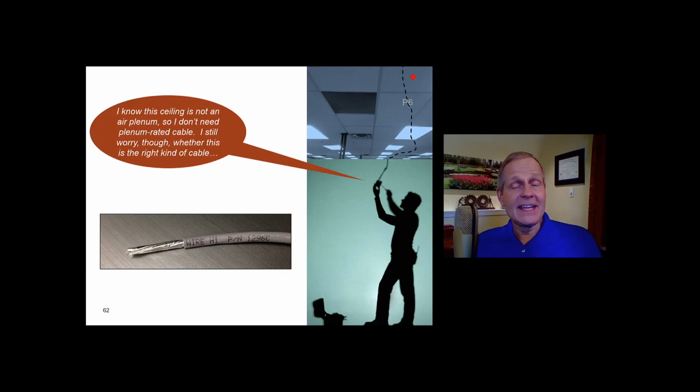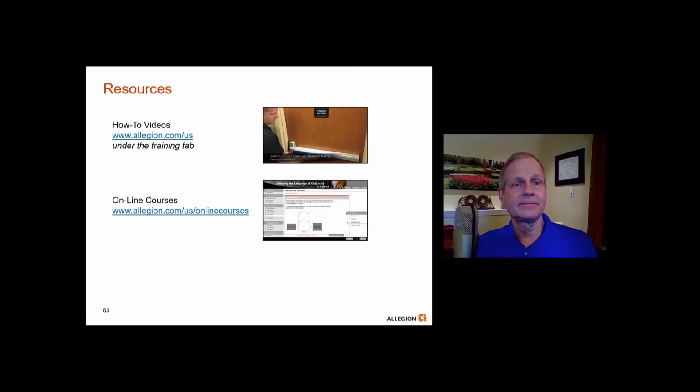Okay, if you said to yourself that yes, you can use it, you would be correct, because this does have the foil jacket on it. So that would mean it's going to mitigate the interference potentially caused by those fluorescent lights.